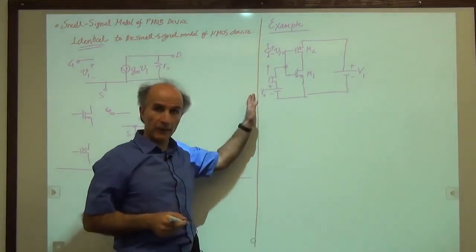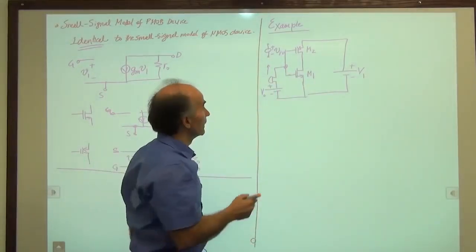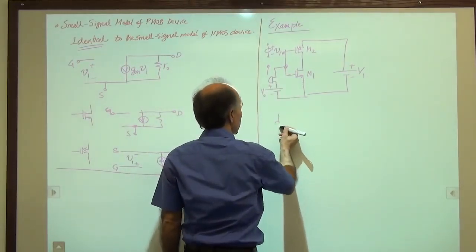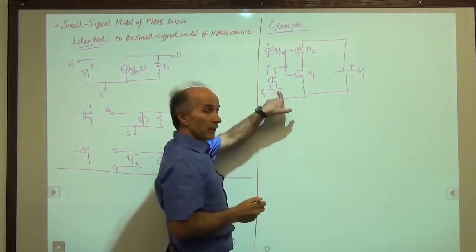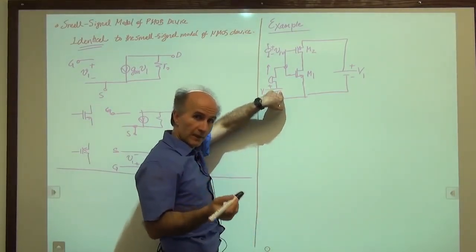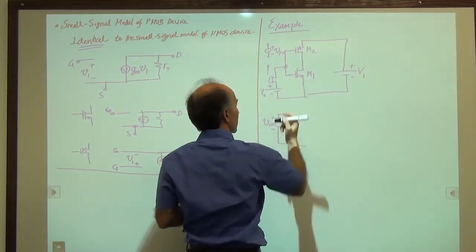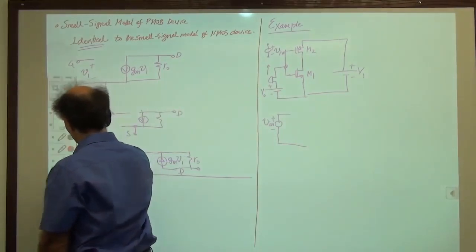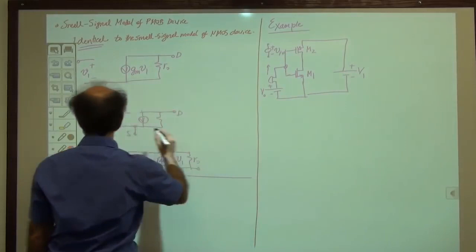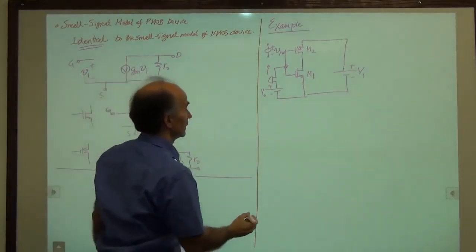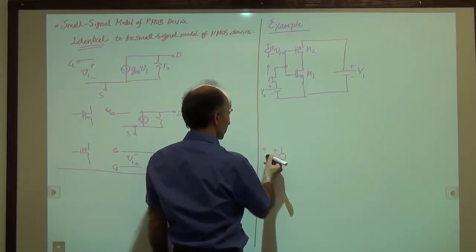Okay, so again, we start from the left and replace everything with this small signal model and go forward. So, microphone becomes a voltage source, very good. The battery doesn't change with time, becomes a 0 voltage source, so a short circuit. The NMOS device, sorry, I have to leave more room for myself, so let me bring this down. So here's the microphone, Vin.